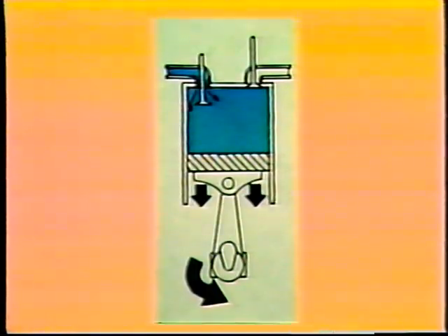When the crankshaft rotates, it pulls down on the piston, and the volume within the cylinder of the compressor increases, reducing the internal air pressure below atmospheric. This intake valve opens, and air at atmospheric pressure fills the chamber. At the bottom of the stroke, when the chamber is filled with air, the intake valve is closed.